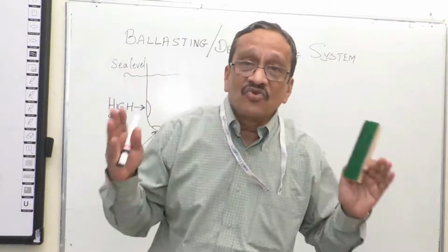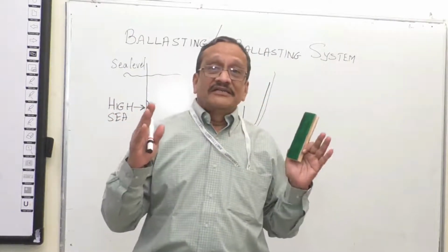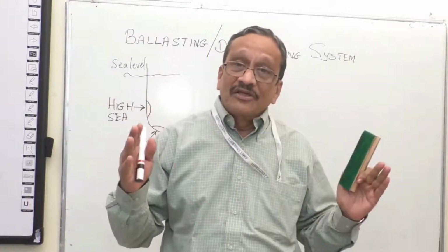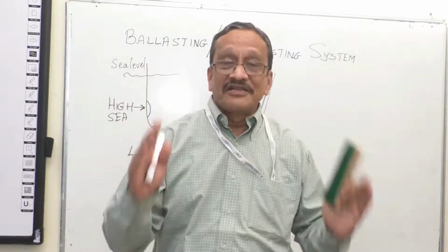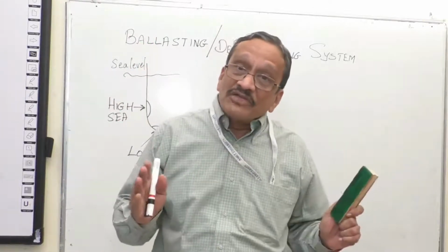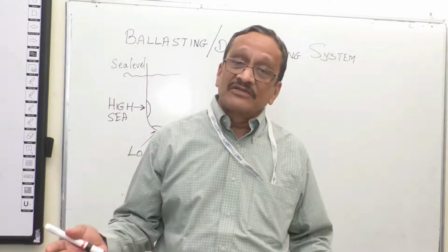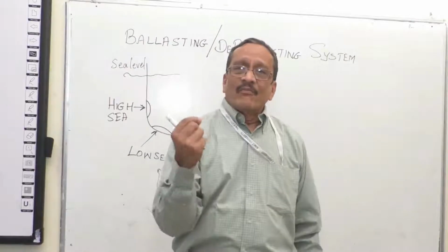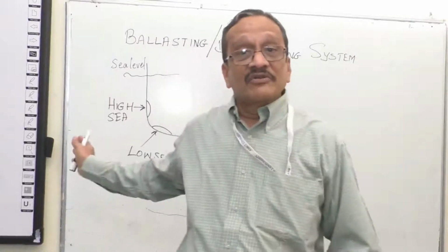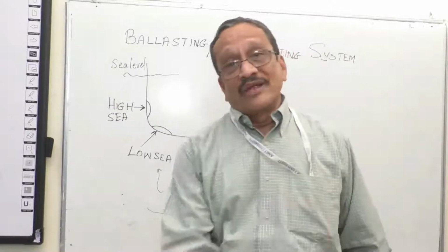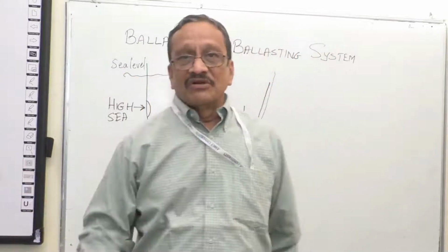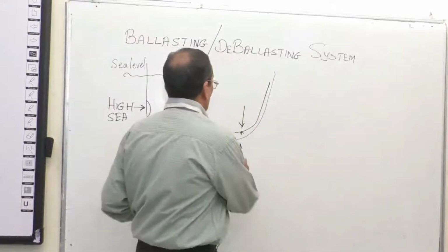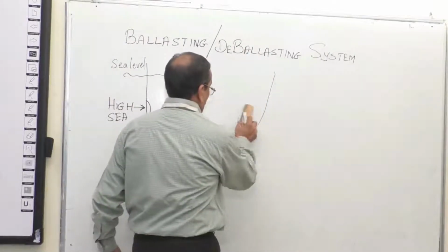We can't afford to lose the strength of your frames, because if they are lost, your ship is in danger. There are all possibilities of your plates getting damaged, mainly because the ribs or the frames have gone, and a minor incident is sufficient enough. Even if the ship is expected to hit bad weather, she'll be ripped off. That's the reason why more importance is given to this. I hope you have understood this. So let us go into the aspects.